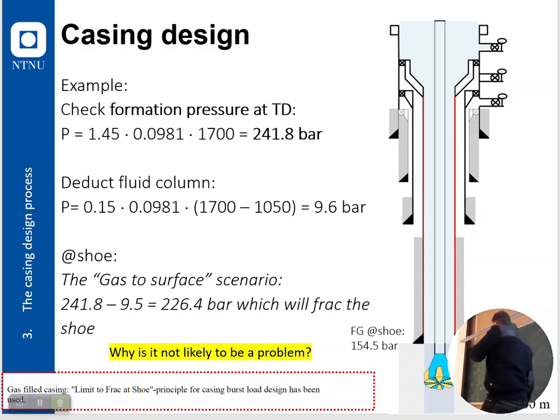Getting back to your question, I want to say no. When we as drilling engineers design, we don't normally get a burst pressure during the next operation. That's why we are doing the design. But of course, there are special cases. I could also think about the casing not being in spec.